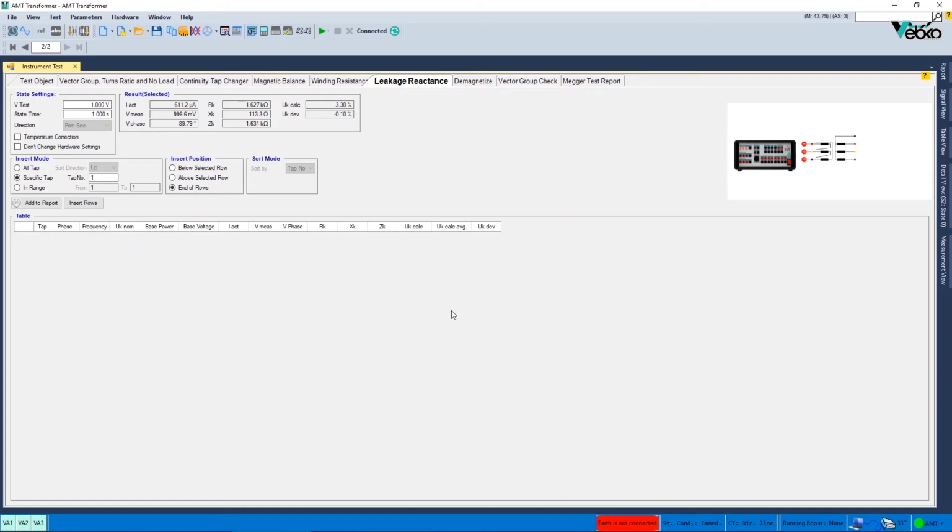The active power absorbed in the short circuit voltage is the same as the transformer losses. The purpose of obtaining the value of the short circuit voltage is to calculate the transformer losses. As the load current increases, the short circuit voltage increases linearly. The short circuit voltage is obtained using the following equation.